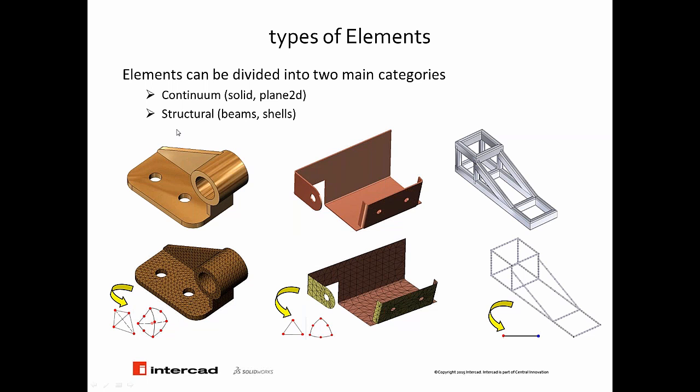But there are some situations where we have a thin fixture geometry, or let's say sheet metal geometry. Well, one dimension, which usually is its thickness, is much smaller than the other two. Therefore, if you need to represent such a CAD geometry in an FEA, you need to use a very small solid element to sit on a thickness and then extrude it through the length. That might generate a lot of elements, and it takes a lot of time to solve.